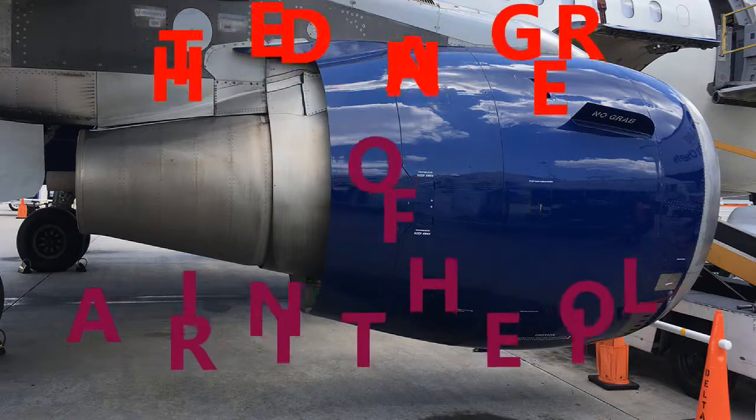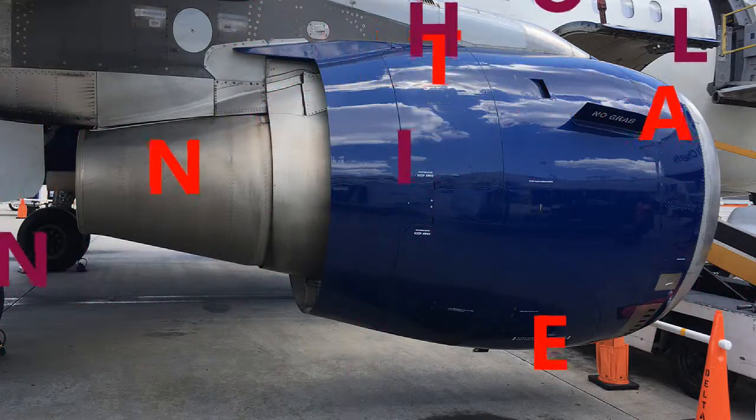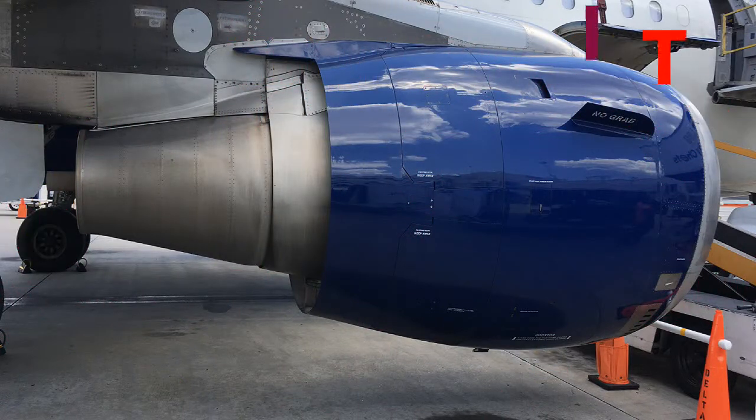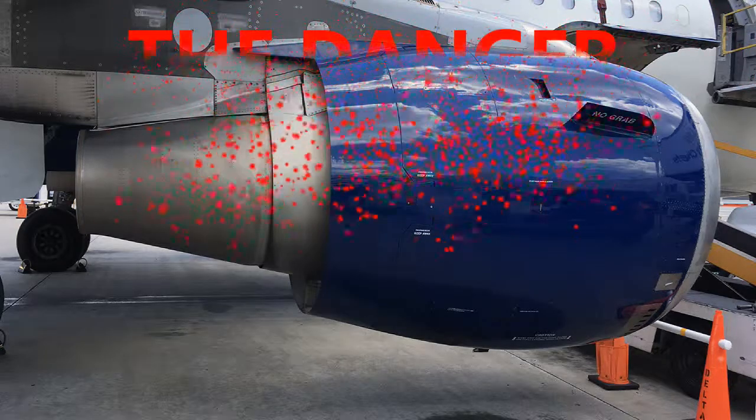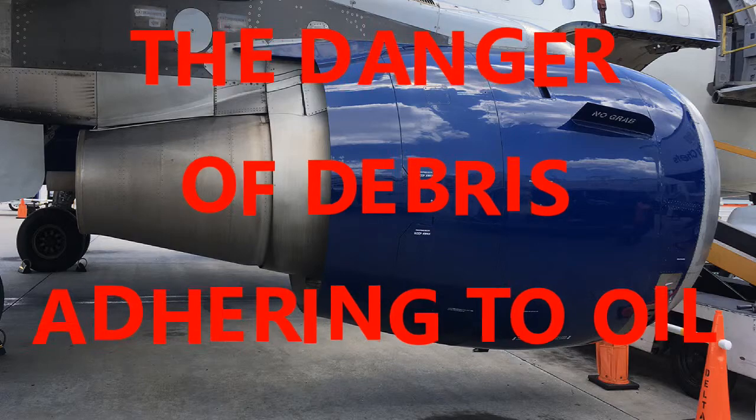The other thing too, the oil can accumulate or attract little debris. Could be little metal chips, little metal particles or particulates that come from just being around the gearboxes and the engines, and we don't want to have that either. So another component of that whole lubrication system circuit is the magnetic chip detectors.